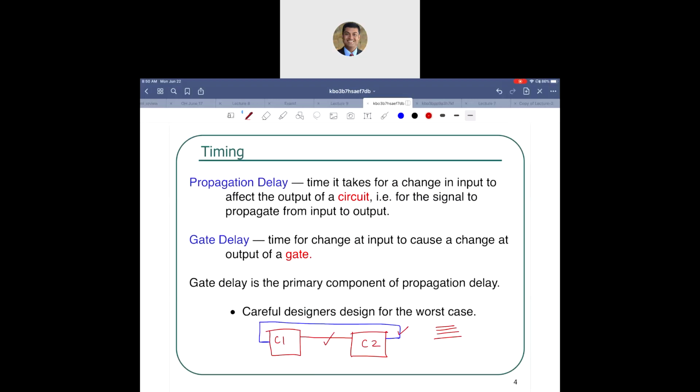So obviously you're calling them a vector or a bus, which means that all these changes need to be happening at the same time. And if all these changes need to happen at the same time, the wire delays should be consistent. All the 4 wires should be of consistent length. But because you are doing this on a printed circuit board, you might not be able to do that because of the nature of where the pins lie.